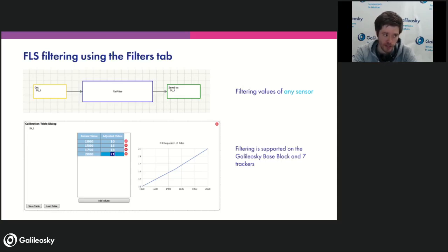So we create get and save parameters. We create the filter itself. That's pretty easy, just 3 different actions. And then we start filling in this calculation table. The calibration process is usually pretty much the same. After we install the fuel level sensor into the fuel tank, well, the fuel tank is usually empty, because cutting into a fuel tank when the fuel is inside is flammable, so it's quite dangerous.